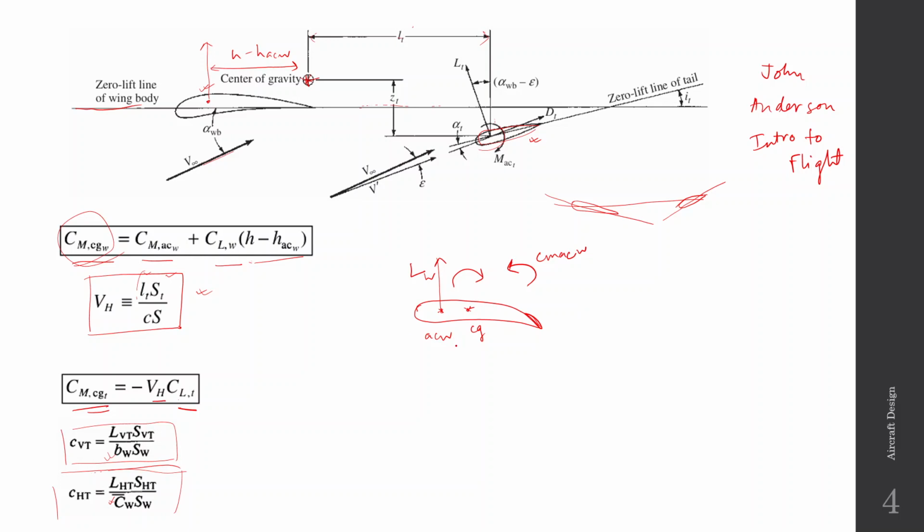Also, one more thing that we studied in the wing placement chapter is that the wings are usually placed at a small setting angle. They may be placed at a setting angle of 2 to 3 degrees, so that during cruise the drag is minimized.